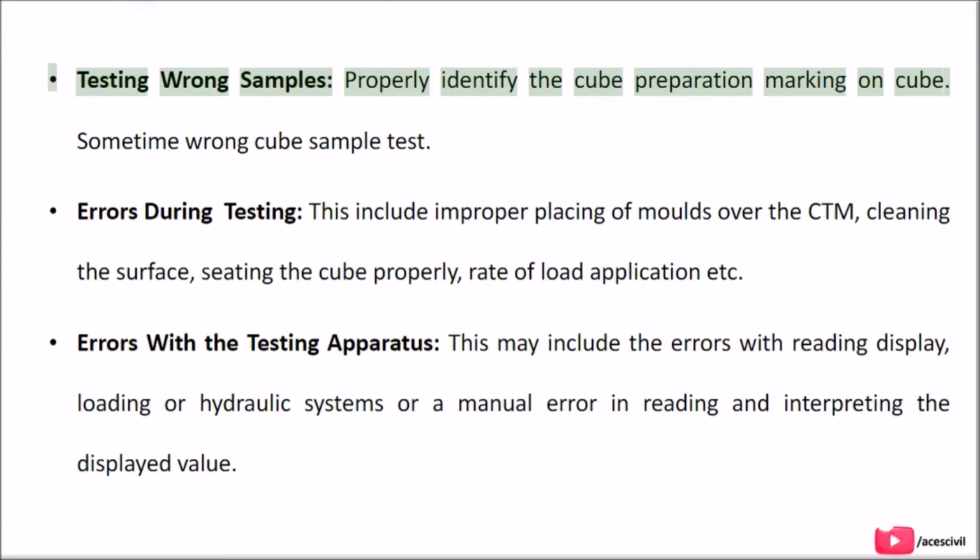Testing wrong samples. Properly identify the cube preparation marking on the cube; sometimes the wrong cube sample is tested.